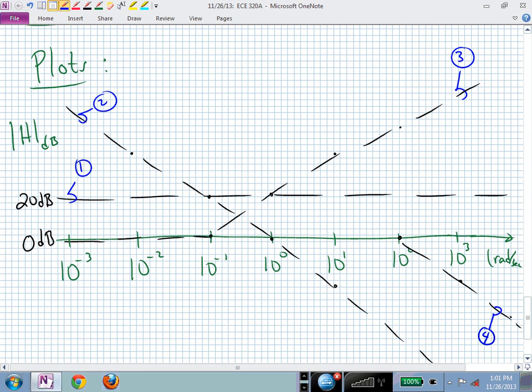If you sketch the Bode plot in MATLAB, it's not going to give you all of these 4 different curves. It's just going to give you the result, magnitude. And we can do that by adding all of these up piece for piece. That's why we're doing it in dB. Now we can add all of these different terms linearly on this particular plot.